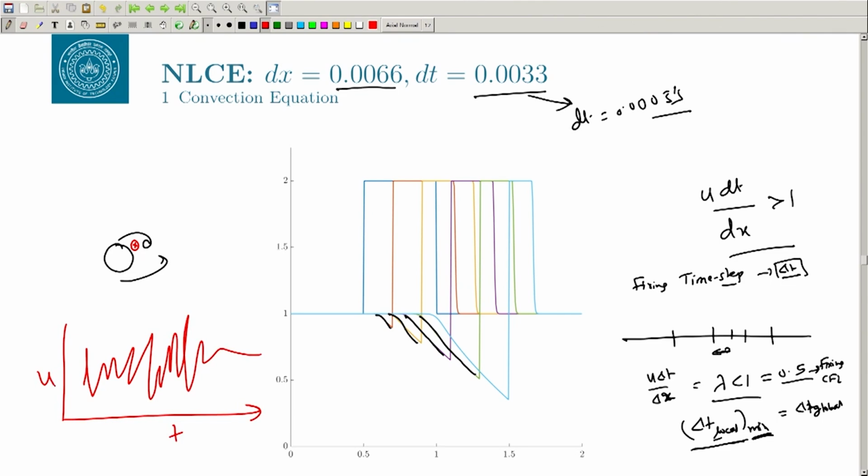And if you want to find out the frequency at which the vortex shedding is happening, you will just do an FFT, the fast Fourier transform of this signal, and it will give you the frequency, or you can just measure it also. If the delta t is fixed, not changing, then you can use this. If the delta t is changing, then you cannot use the FFT, because your delta t itself is not fixed. So, the 1 by delta t which gives you the frequency is not fixed, because delta t is changing in every time step, right.